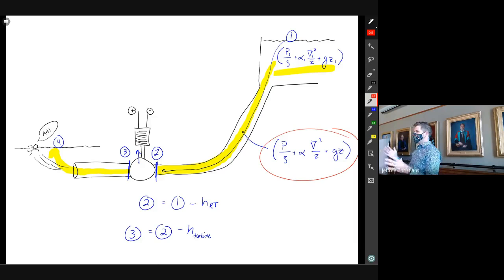If you change the minor loss coefficient, the K values, if you double it, does it matter? How much? If you cut it in half, how much does that matter? Even in as short as 20 minutes, you'll get a feel for what things make big changes and what things make little changes. And you can start to key in on what we really need to focus on to get our system optimized, the things of first priority versus the things of third priority.